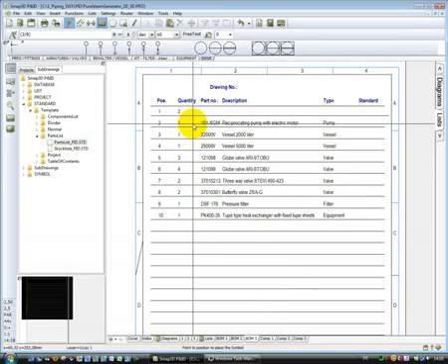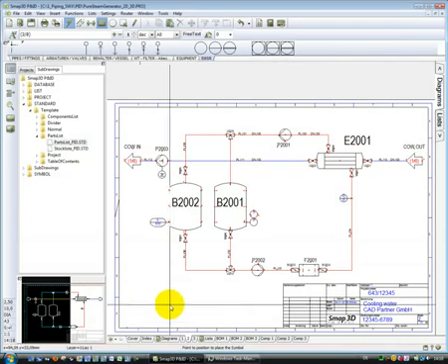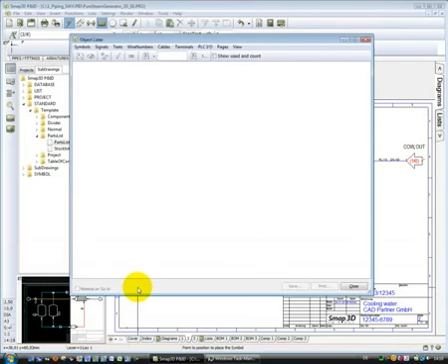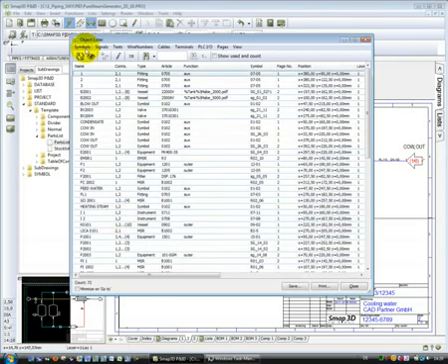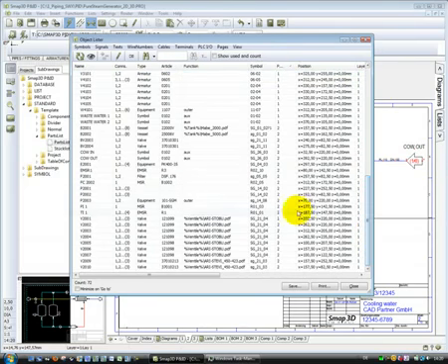And if I like to solve this, I can do this very easy. So I go to my sheet back and use a function called object lister with the short key and the F7 button. Then I come in this mask, and in this mask I can select the display of all available symbols. In this object lister I can, for example, sort about every available column, and if I like to see here all the content of page number 2, then I can see this, and here in the other columns I can see all other information which are available.